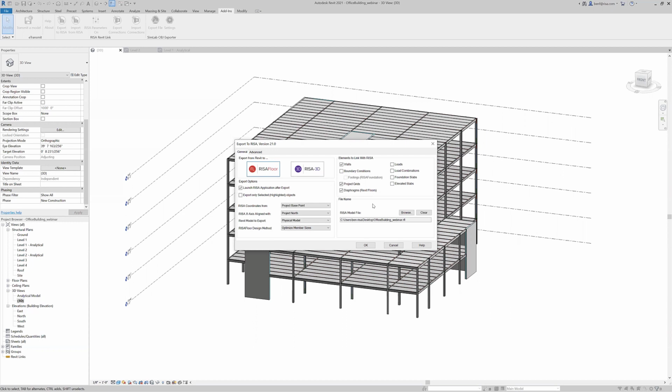The mapping table is basically an Excel file that says, this family in Revit is matched to this profile shape in the profile library in RISA. And so we'll see the transfer. That's why this transfer happens one-to-one. That's part of the API.